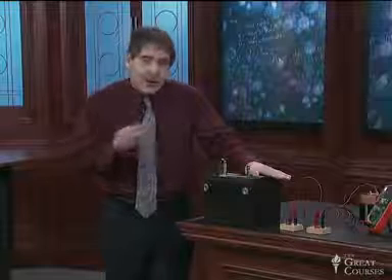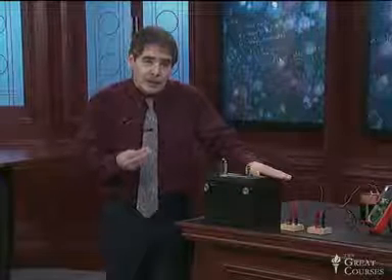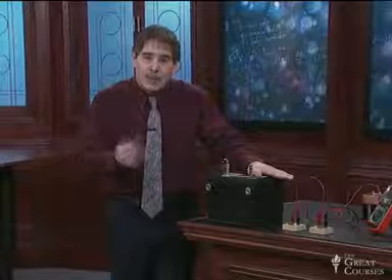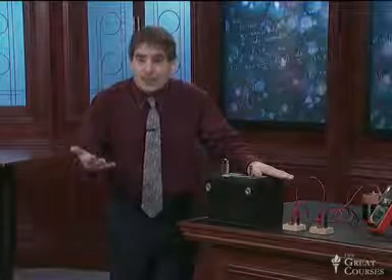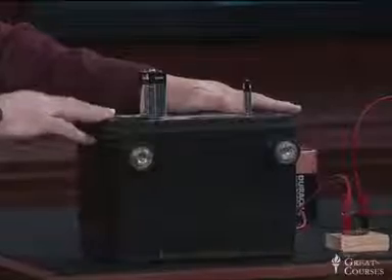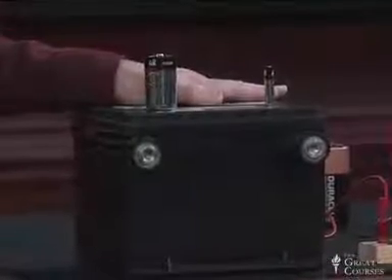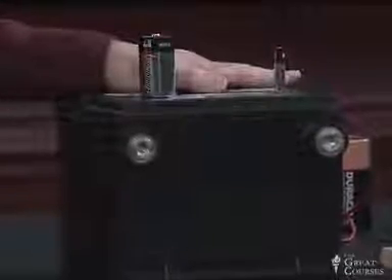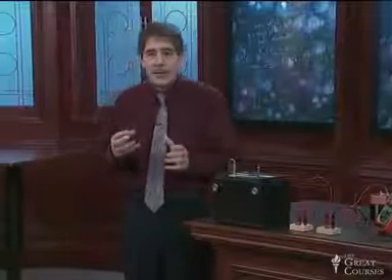And that takes a very, very low internal resistance, because if you had any significant resistance, if you had 1 ohm, you'd try to drop 100 volts across that. You couldn't do that because the internal battery is only 12 volts. But you get the idea. The internal resistance of the battery has to be a tiny, tiny fraction of an ohm in order to supply those very huge currents. So this whole idea of internal resistance is what distinguishes real batteries from ideal ones.